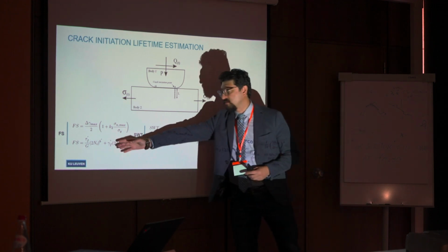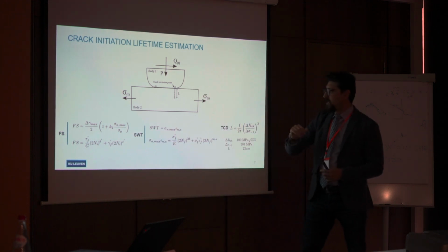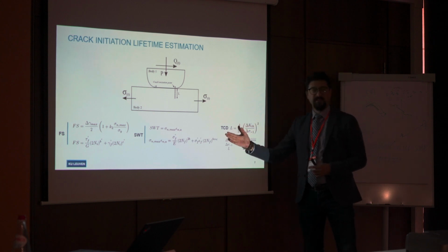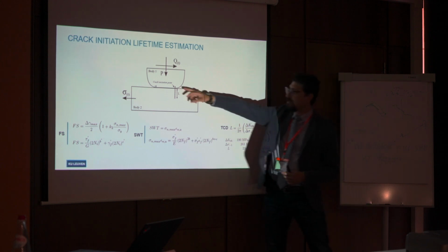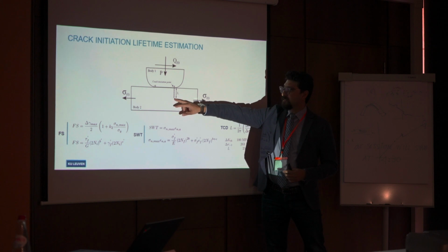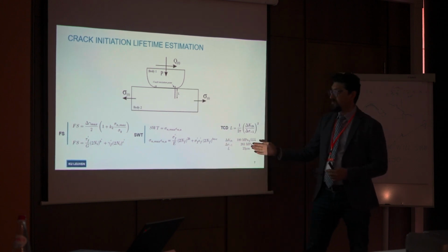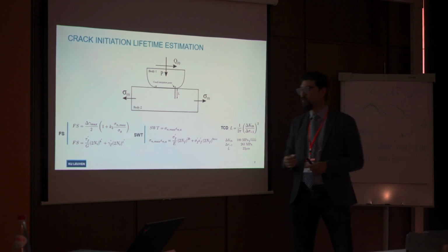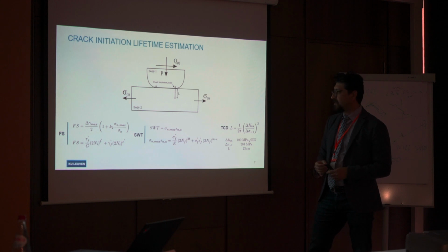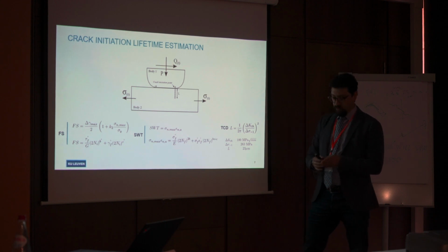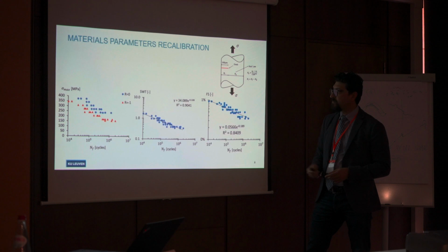We use Talemi FS and SWT parameters. We combine that with theory of critical distance to extract data at the critical distance of L, depending on the material that we use. We use, let's say, these material properties. We use aluminum 2024 T3 in that application, and we try this method to predict the crack initiation line.